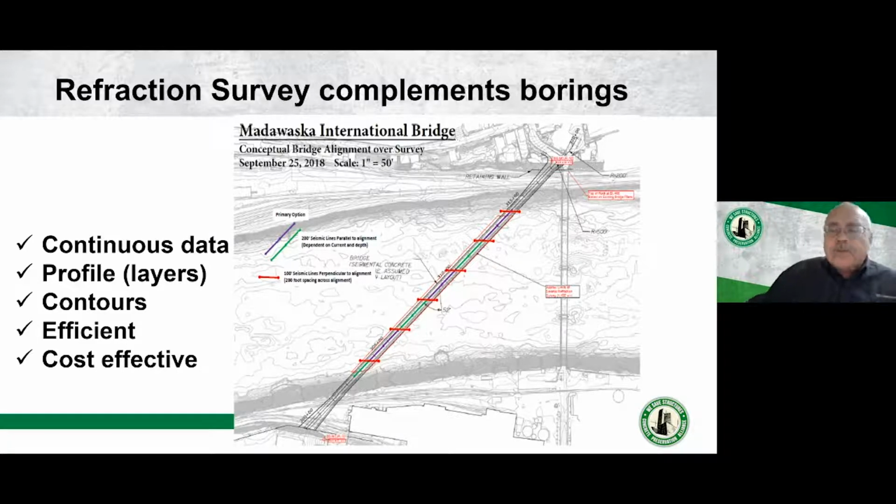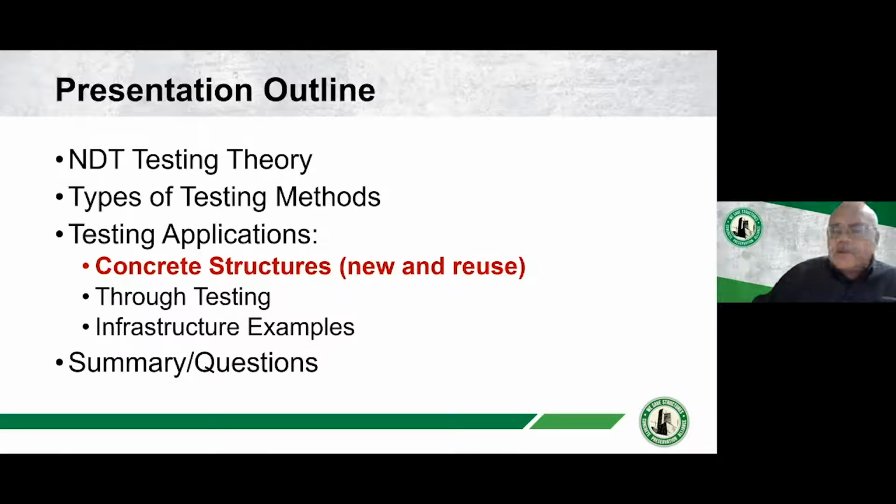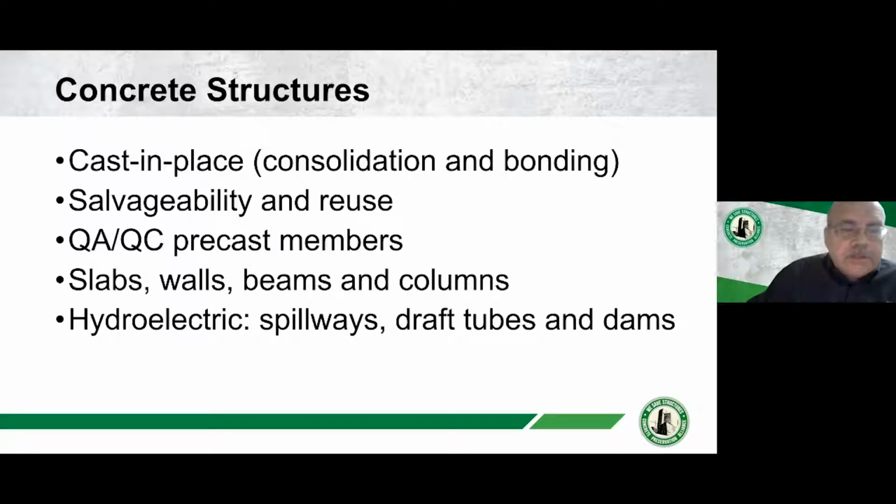They were preliminary geotechnical design. They could still determine, is it a shallow, deep foundation, even change some of the span lengths based on this preliminary information. So we're going to go into some testing applications, starting with concrete structures, the new and the reuse.